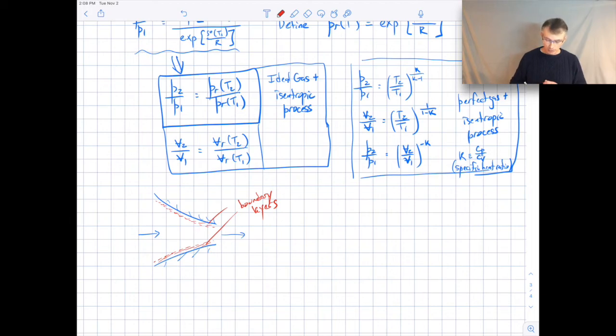Okay, so when you have viscosity coupled with a large change in velocity, you get a lot of energy dissipation. So in those red regions here, those boundary layers, you get lots of energy dissipated. Outside of the boundary layers, the velocity gradients are pretty small, and even if you have some viscosity, it doesn't play as much of a role. The energy dissipation is related to the viscosity times a function of the velocity gradient. So if the velocity gradient is pretty small, you don't have very much energy dissipation. So actually inside here, there's very little dissipative behavior. It's essentially an internally reversible flow in this region.